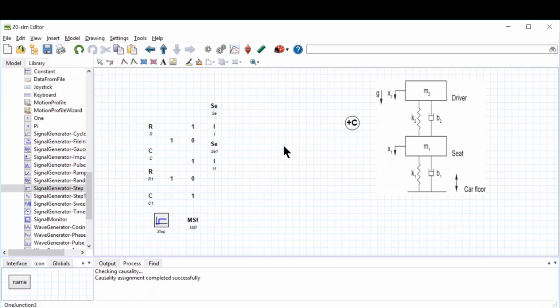If I don't connect them, they don't communicate to each other in terms of transferring the energy and interact and give me the dynamic representation of this mechanical system. So how do we connect? For connection, you have two ways. Actually, you can come here and activate the connector, or you can simply press the space bar on your keyboard if you have. So either way is fine. I just click and unclick, spacebar, activate, deactivate, or you can click here.